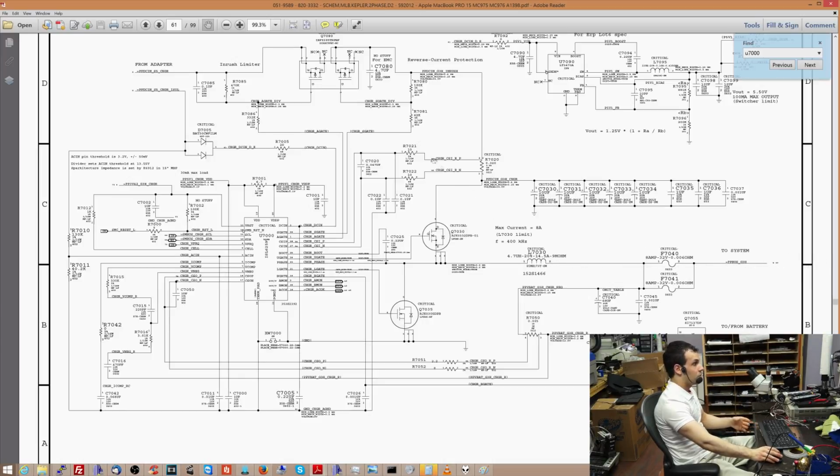Now, a short can be anywhere in the circuit where it's stopping the power short. So, for example, let's say one of these transistors, let's say this one over here, instead of opening and closing when this chip tells it to, is shorted to ground. Let's say this has a 0 ohm resistance to ground at all times. So instead of this power making its way all the way over here, it gets stopped short right over here, because it has a 0 ohm resistance to ground because this transistor decided to die. This thing over here represents ground, where you see those 3 lines. And this is going to stop the power from making it over here.